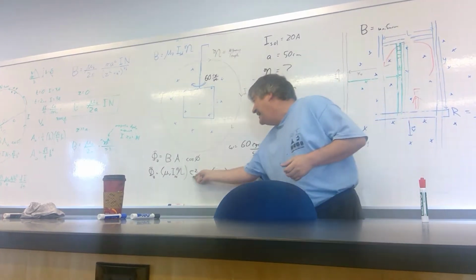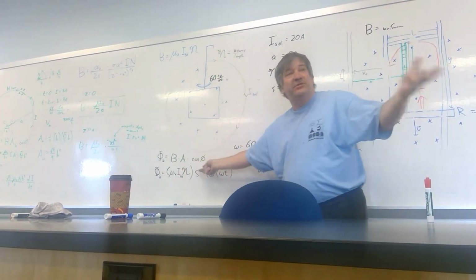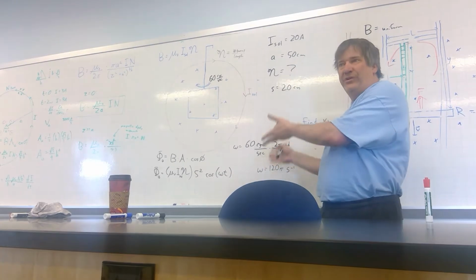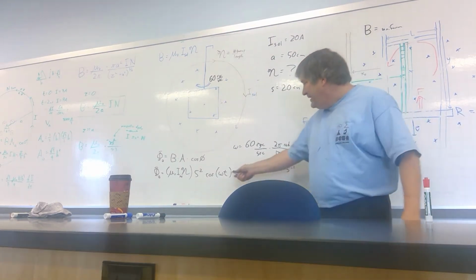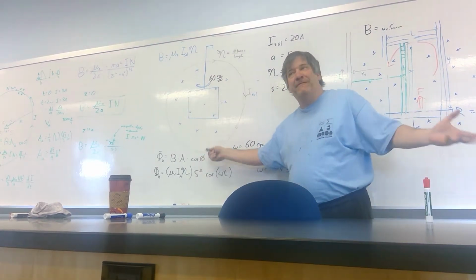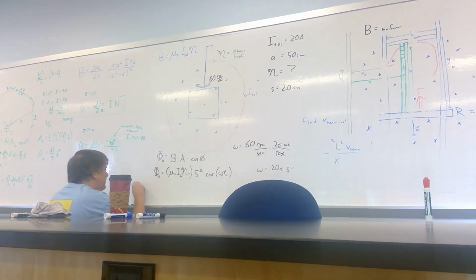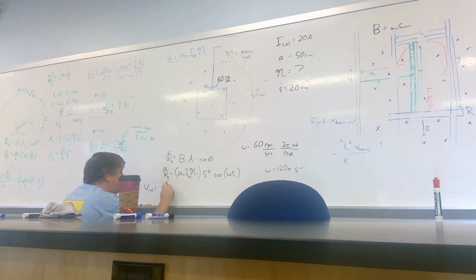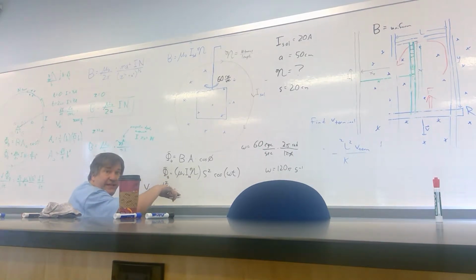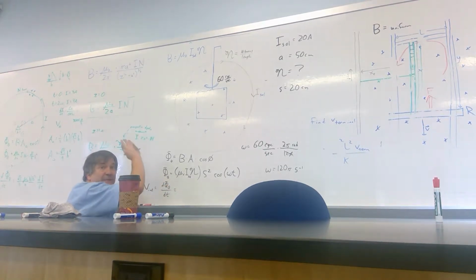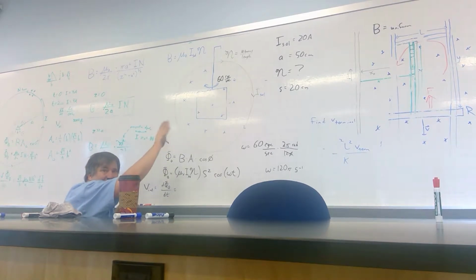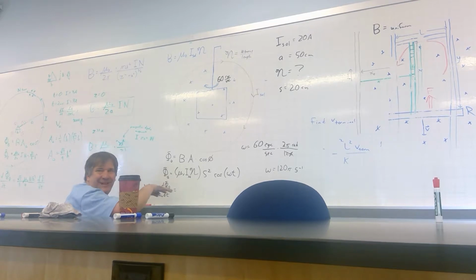But yeah, anything that does appear in my calculations, if any of these things were changing with respect to time, that could be how we're turning this into an induction problem. In this case, the only thing that's changing with respect to time was that phi. So the induced voltage, as always, is going to be d flux dt. Strictly speaking, I might be writing V induced as negative d flux dt, but again, the negative sign, unless I've been paying close attention to my sign conventions all along, it's probably too late at this stage in the problem to start paying attention to plus and minus signs.